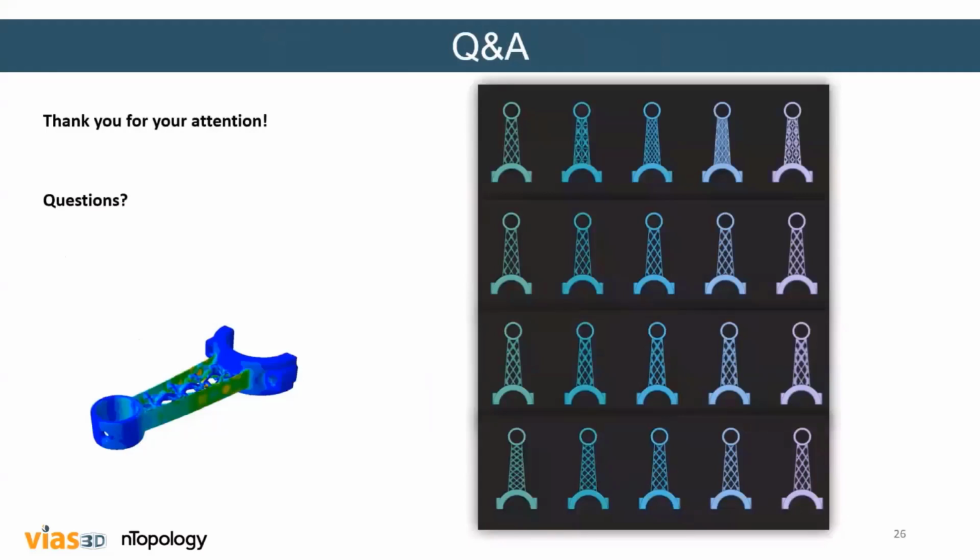First, is the geometry modified in Tosca or in nTop? So the final geometry modification around the fatigue life was done in Tosca. It does not have to be sent back to nTop. It's performed on the mesh. But there is certainly a geometry generation occurring, with all of these design variables you see on the screen, in nTopology.